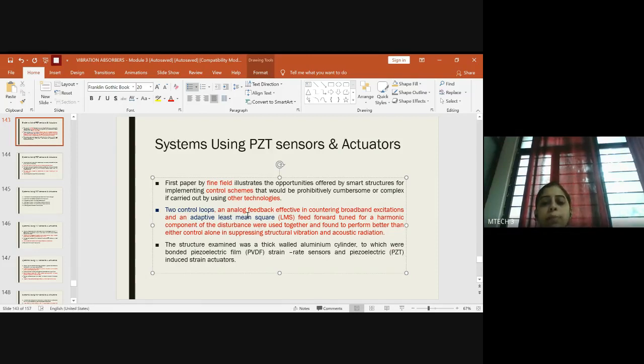So all the vibrations and the acoustic radiations which disturb the actual phenomena could be overcome. He tells that one loop is needed to see that the work is done properly, and another loop to eliminate the disturbances, so that the noise will not disturb the effective measurement of either strain, stress, temperature, pressure, or whatever you are using it for.